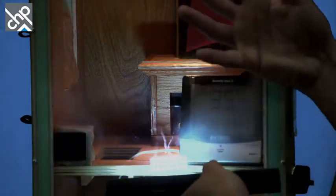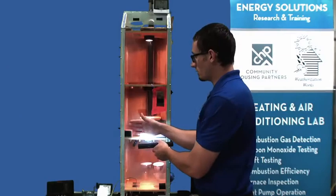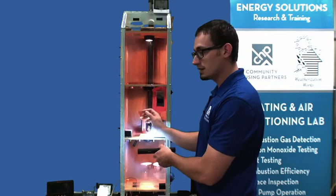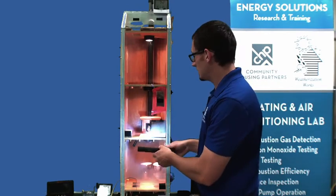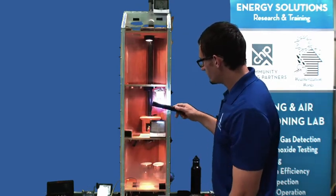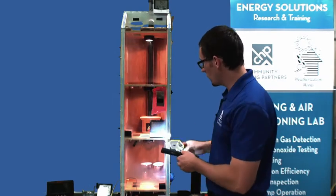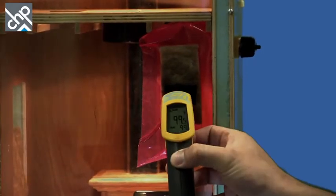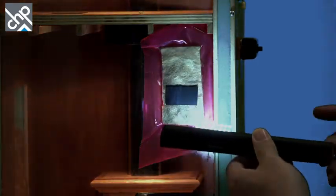So that's, again, showing you that without a proper air barrier system around this fiberglass, that air is going to move through, and then if it hits a condensing surface, it's going to condense. So if we look over here, we have something that's even lower. It's 99 degrees. And by the way, our dew point is 109 degrees. So 99 degrees there. But there's no condensation.